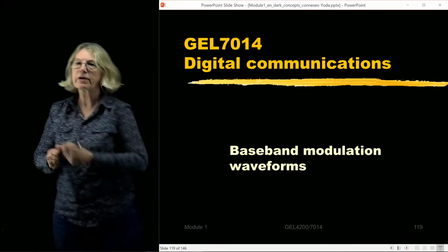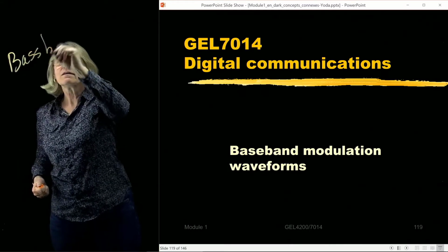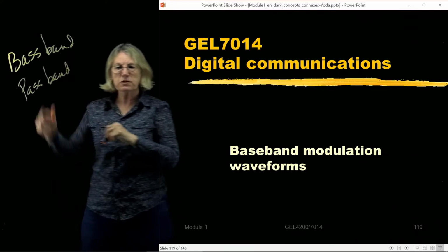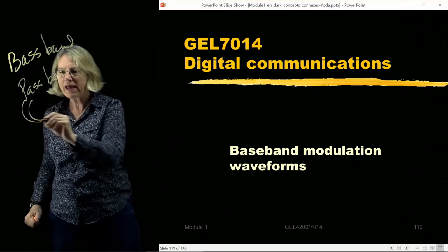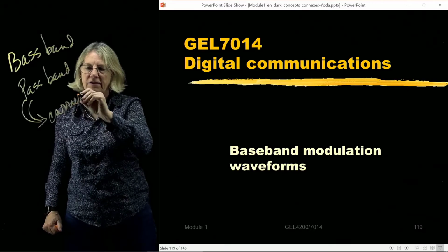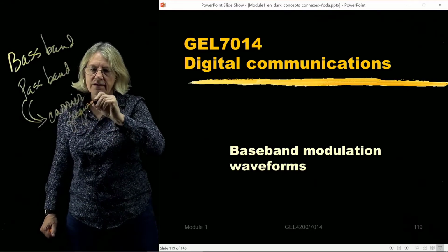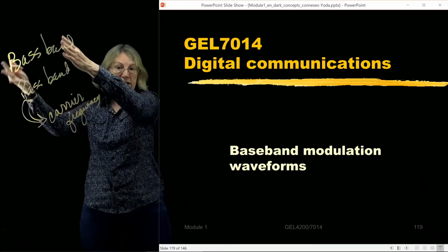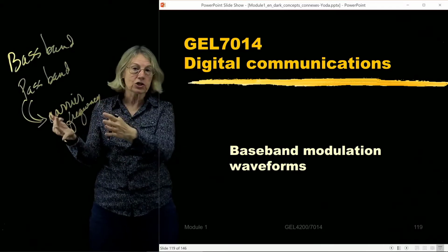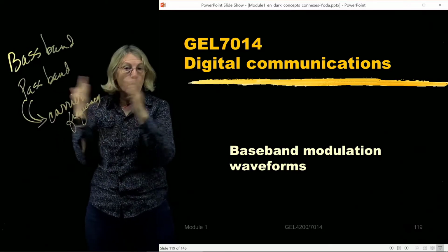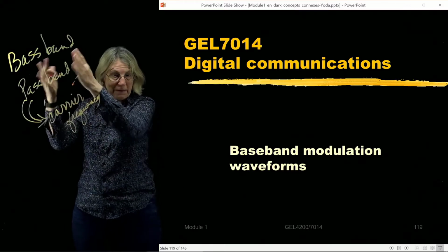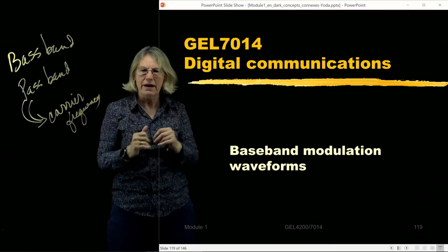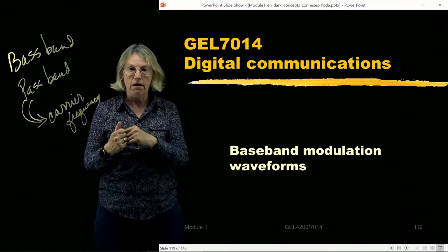There's two things. We can have what we call baseband, or we could have passband. Two types of communications. The difference between baseband and passband is that the passband uses a carrier frequency. That means instead of having the information be centered at DC, which we call baseband, it will be like a cellular telephone where we take the voice, which is typically baseband, and we put it up on a higher frequency, like 900 megahertz or something, for the actual transmission by RF means.